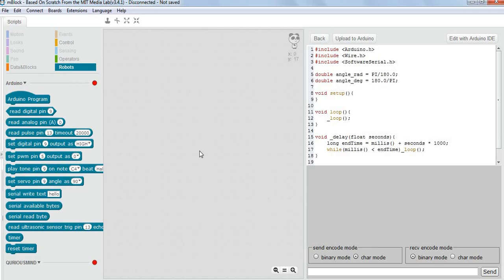The first thing we need to understand here is that the direction, we have only two values. Either it can be clockwise or it can be anti-clockwise. And to control this direction, we need to make the pin either positive or negative, which means we have only two values for direction, and that means they are digital values.